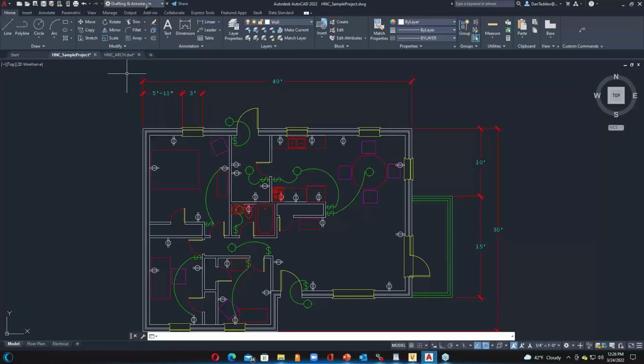So all of the things that we want to customize and save and tailor for our needs, we need to be able to save either as a profile file to save all the configurations and the mappings that we've done in terms of where the template files are, where our tool palettes are, or if we're going to be working with workspace, we want to save this as a profile. I'm sorry, a workspace setting, so that we can recall those, right?